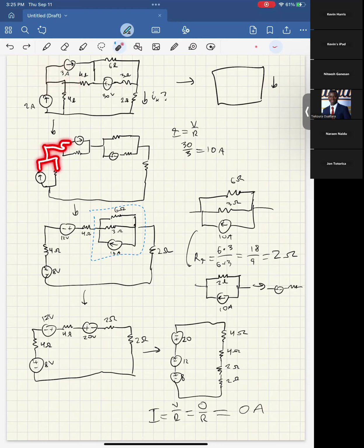Here we have the same thing, right? These four components are all connected by a wire. I just redrew it like this because compartmentalizing each of these current source resistor pairs into their own separate section makes more sense when you go to do a source transformation later. Again, that's the same thing here. This is connected, this is connected, this is connected, this is connected. It's all one wire. When I say one wire, I just mean they're all connected only by wires with no resistors or anything between them. Because if you think to the lab part of the class, if two things are connected by a wire, then there's no voltage difference between them.